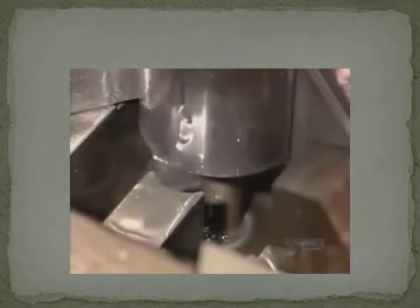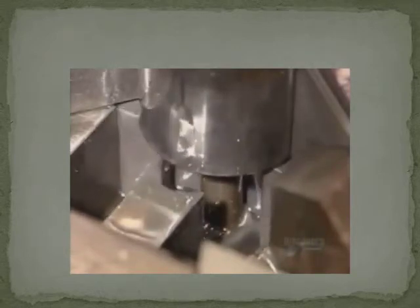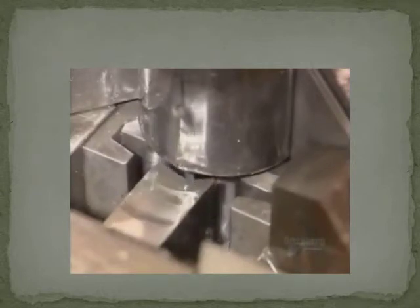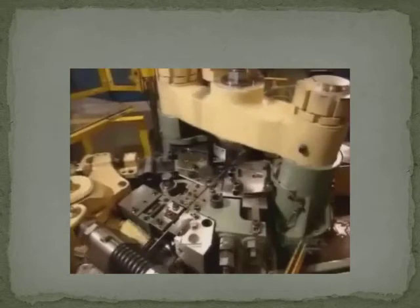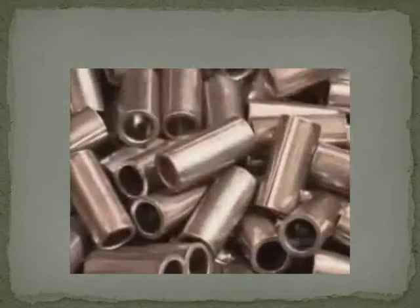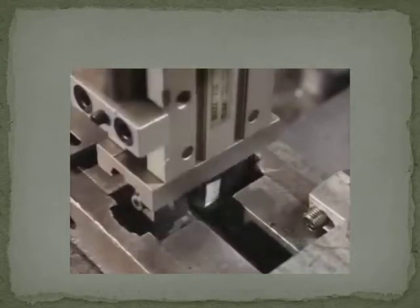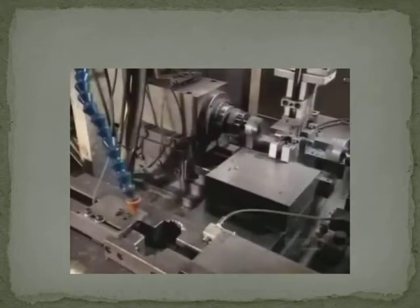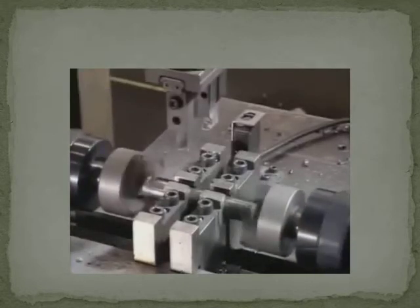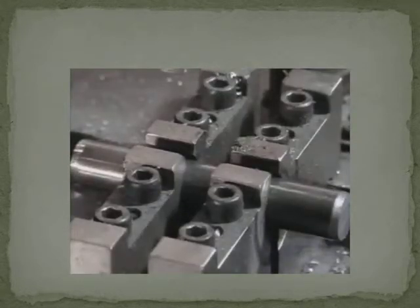Then, the next process is to fabricate the bushing and roller of the chain. The process involved is the drawing process. Next is to fabricate the bearing pins of the chain. The rod will be cut into a desired size and both ends of the pin will be chamfered so that it is easy for the assembly process.